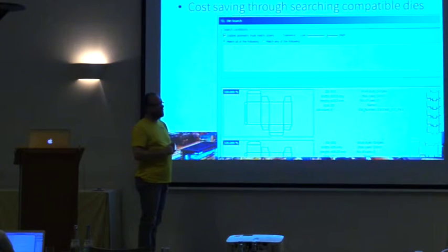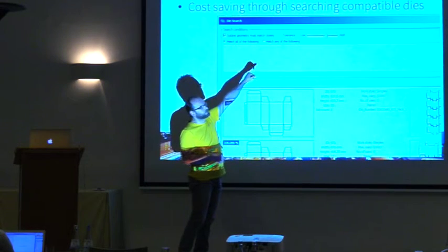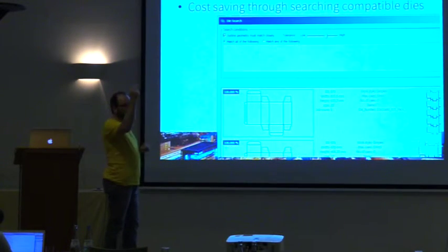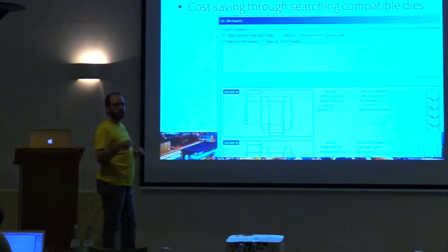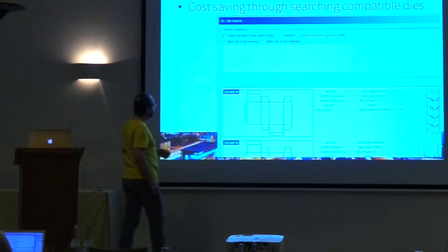When I have a new job coming in, I can ask IMP, and you have some settings to see how close the match needs to be and so on. I can ask IMP to run through my die database and see if there is something that comes close to what I have produced in the past. The idea, of course, is that you could find something that is a good match, and you could avoid having to make a new die because you still have one that is close enough for what you need.